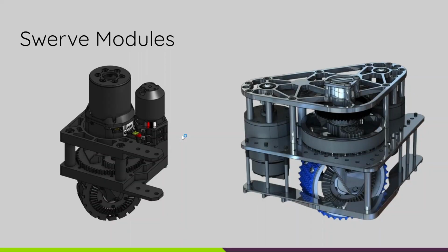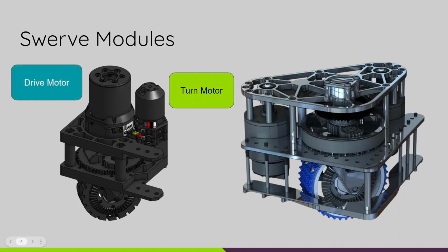These are what the individual Swerve modules look like. There's multiple different kinds of Swerve modules, and the basic idea is that one motor turns the wheel and the other one drives it. So you can have mechanically many different kinds of configurations of these motors and gears to turn these things. Here you can see the motors are underneath. These are MK4Is, whereas these are Rev Max Swerve, and it's what our team uses.